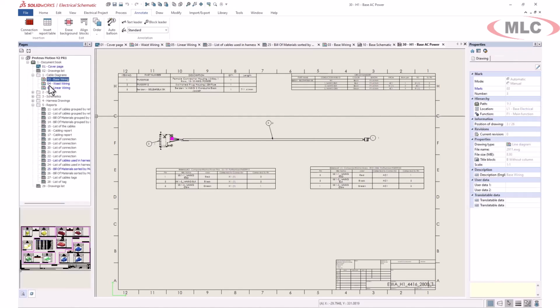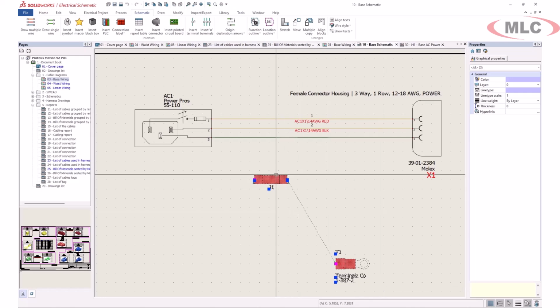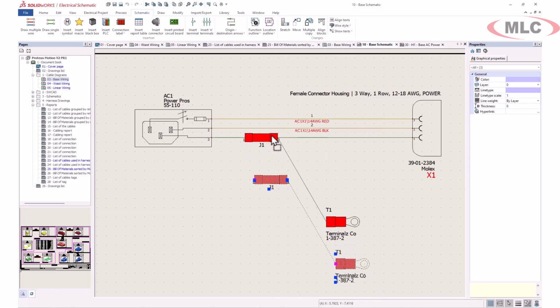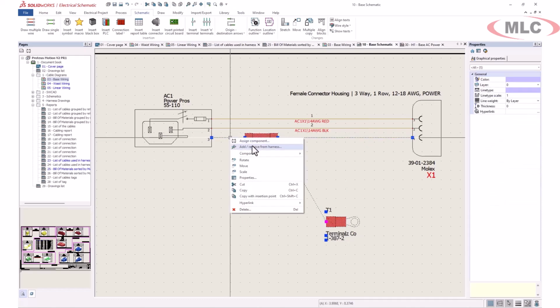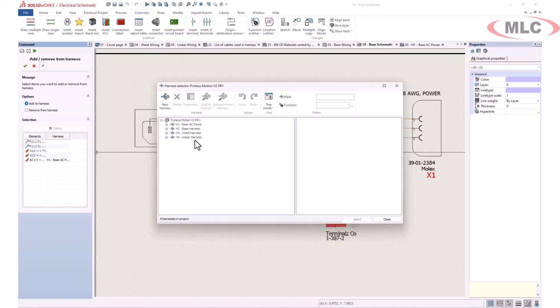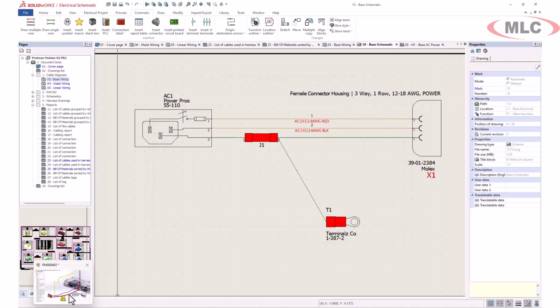Alright, the project drawing looks all nice and pretty, but how about we do some design? One task today is to add a splice to extend my ground loop directly to the chassis. This means I will have to update the 2D design, the 3D route, and the flattened harness drawing. Let's start by finishing the schematic representation, extending the ground circuit to the chassis via a ring terminal.